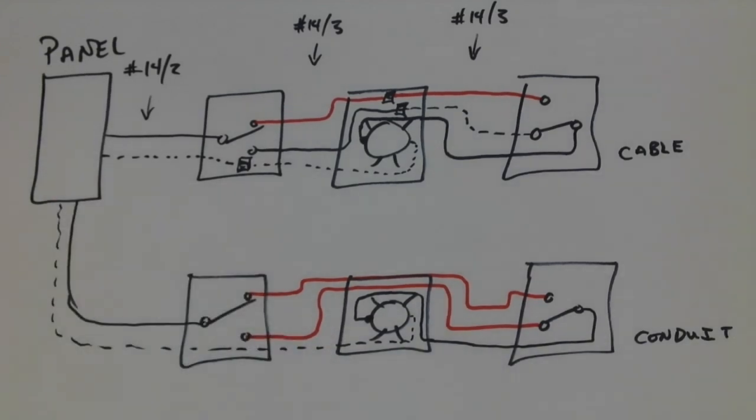And so here we have the conduit installation, and you can see very obviously there is no identified or neutral connection back to this switch box. So keep in mind how some of these legacy installations were wired, because at some point it may be quite probable that you will have to troubleshoot something that you may not have had an immense amount of experience with.